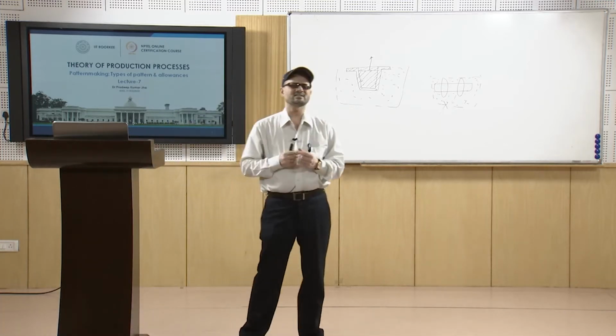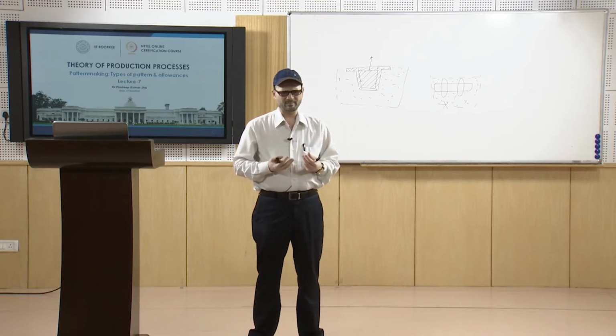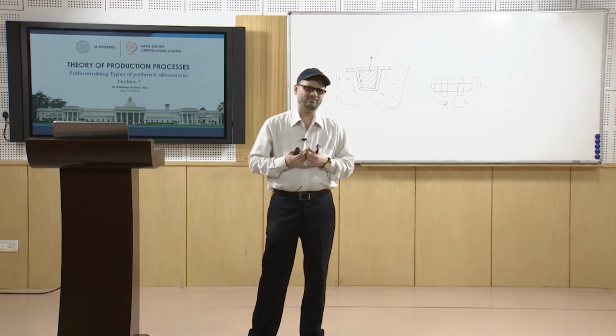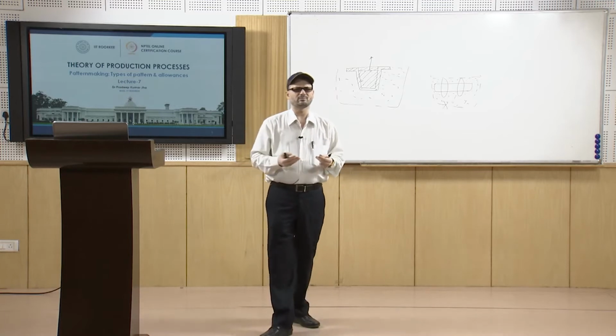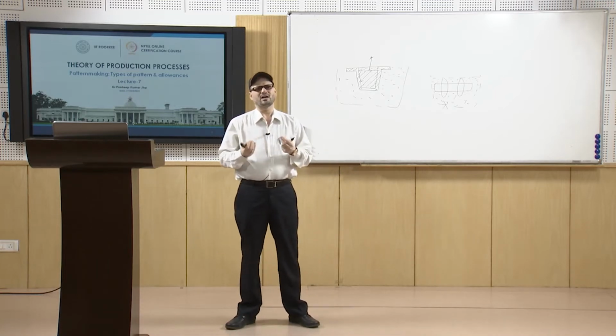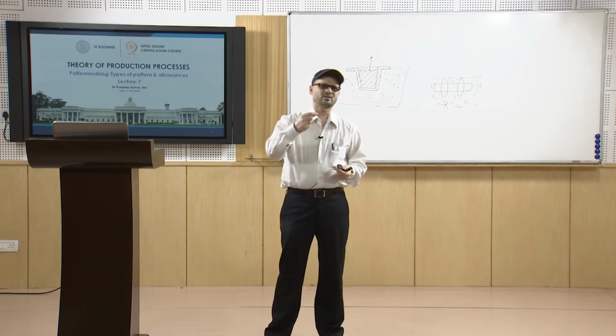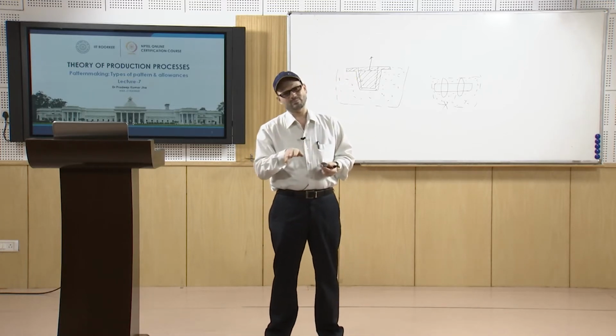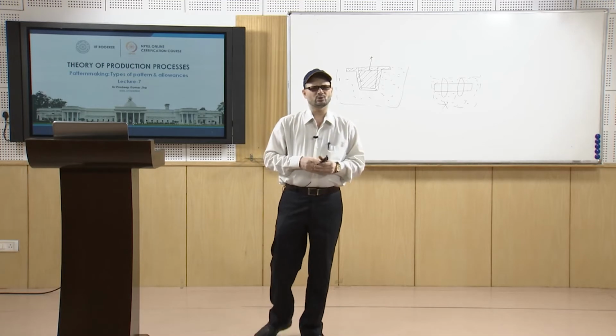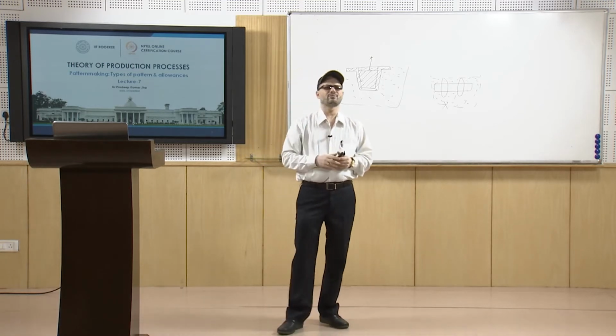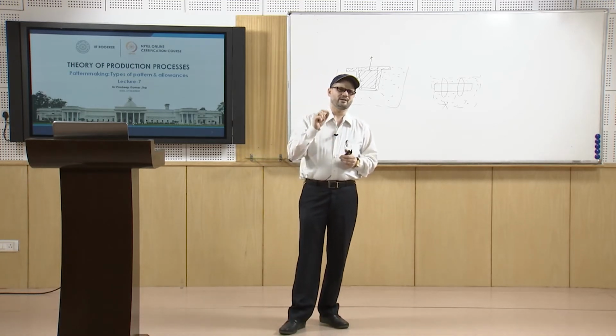Hand cutting certainly will take time, and it will also have certain problems, because many a times because of the hand cutting, maybe the sand which is removed may go into the cavity. So that will be a source of defect itself in the casting.